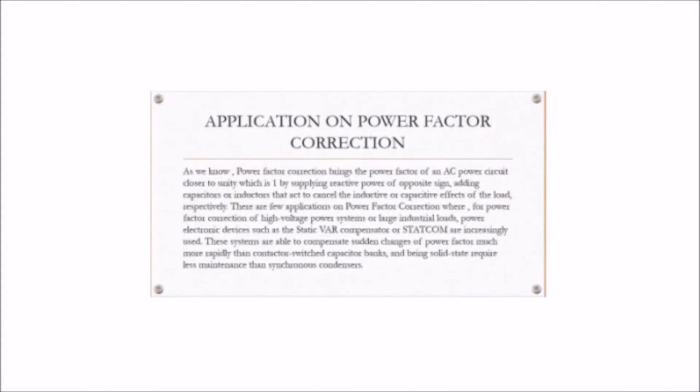As we know, power factor correction brings the power factor of an AC power circuit closer to unity, which is done by supplying reactive power of opposite sign, adding capacitors or inductors that act to cancel the inductive or capacitive effects of the load, respectively.